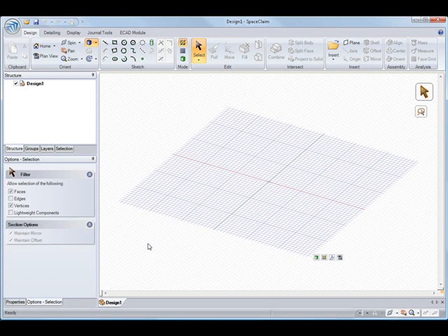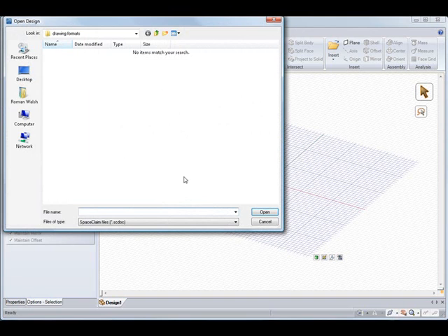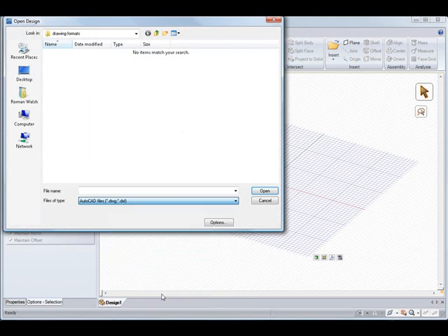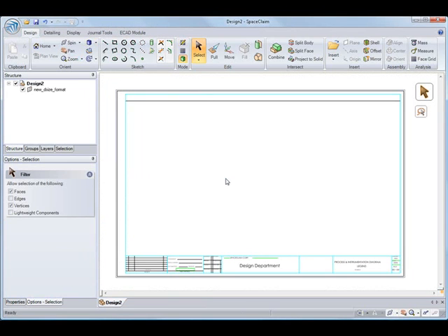Hi everybody. Today we're going to be focusing on drawing sheets, specifically bringing in a DWG from another system and making that your default drawing sheet. So right now I'm just going to open up a DWG. See, I have one titled New D-Size Format, and we'll just bring it in to look at it. So I like this, and I'm going to use that for my format.